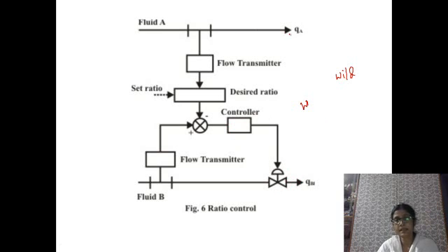This is purely the uncontrolled path, and comparing its measurement with the set value, the other fluid flow path is maintained as the control flow path with the desired ratio. So that will be the other fluid output, which is actually the input to the process plant.